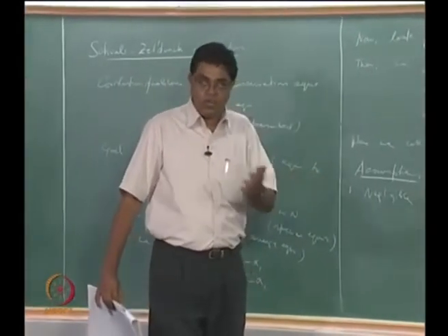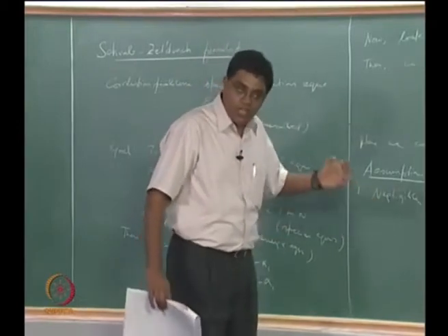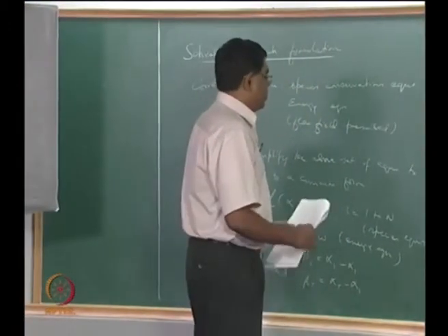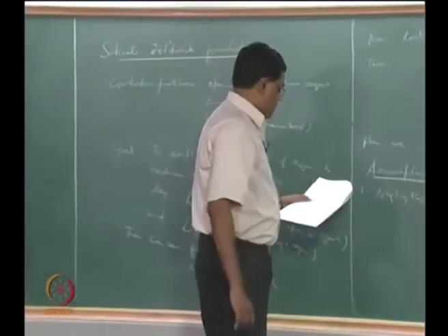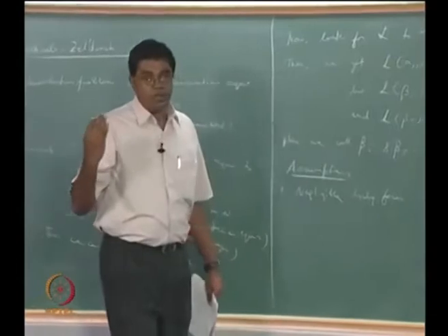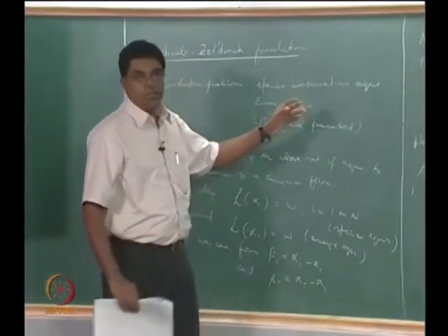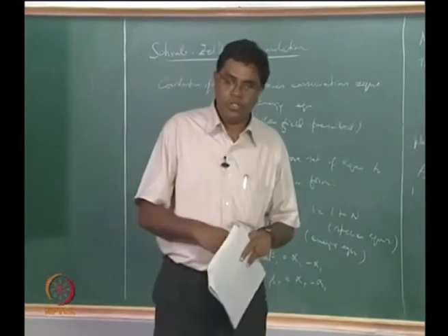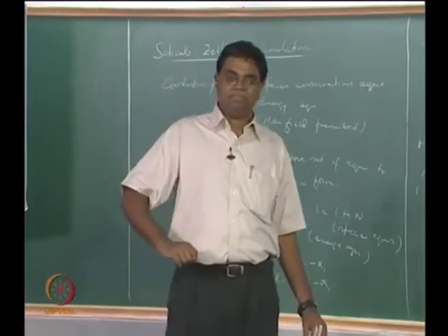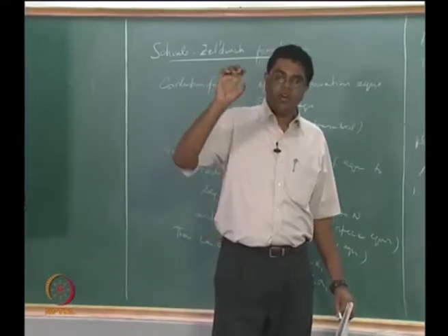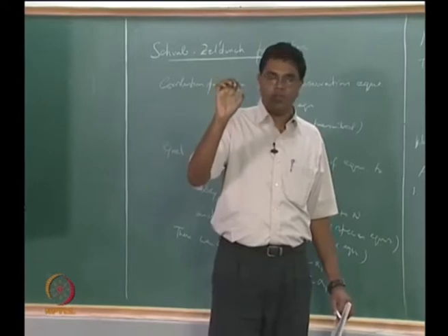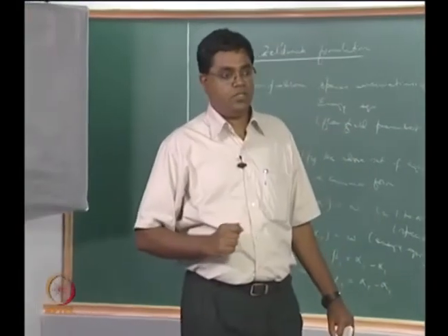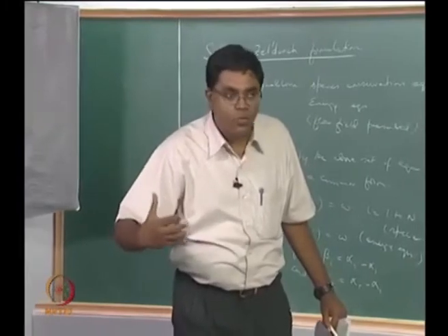Alright, that's great. That means you can actually get the adiabatic flame temperatures predicted fairly well, and then your formulation should be able to show the temperature in your flow field. So that's pretty good. Here the reason why we want to actually neglect body forces is it shows up in the multi-component diffusion equation, right. So our goal is to try to simplify the multi-component diffusion equation to look like Fick's law, so that we can directly substitute the Fick's law form into the species conservation equation right away, just like how we did it the first time for a binary mixture. Then we don't have to deal with the multi-component diffusion equation separately anymore.